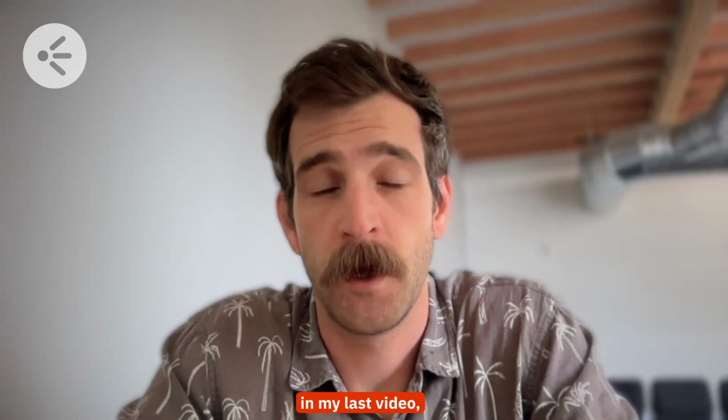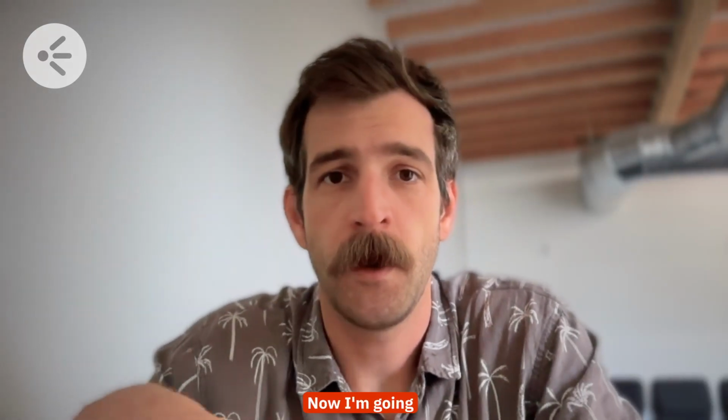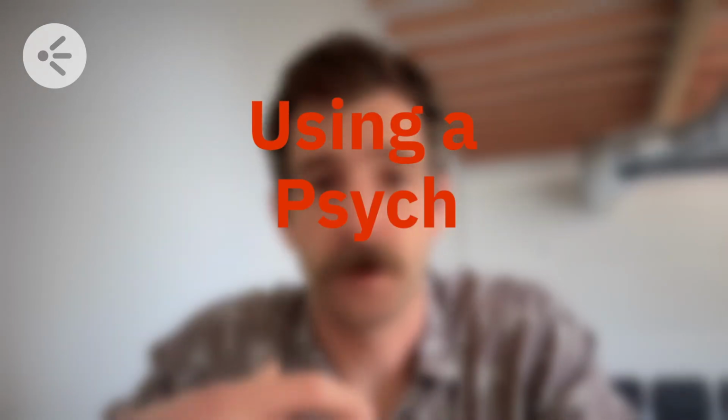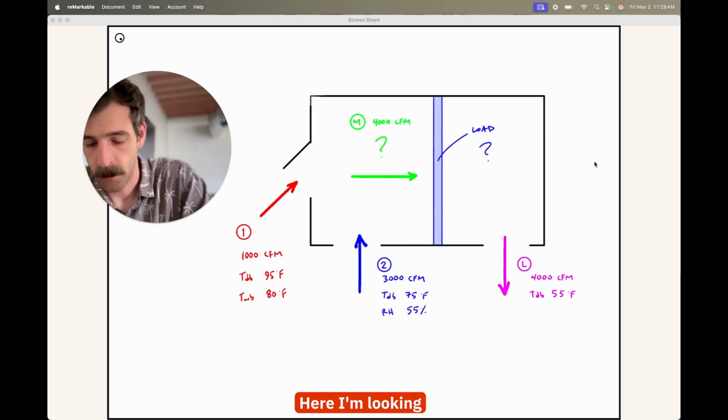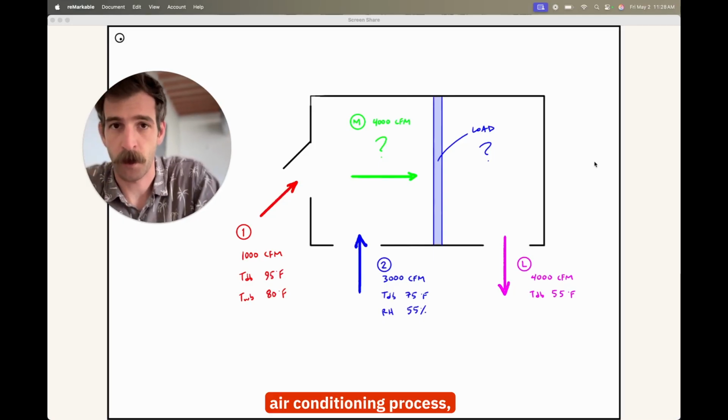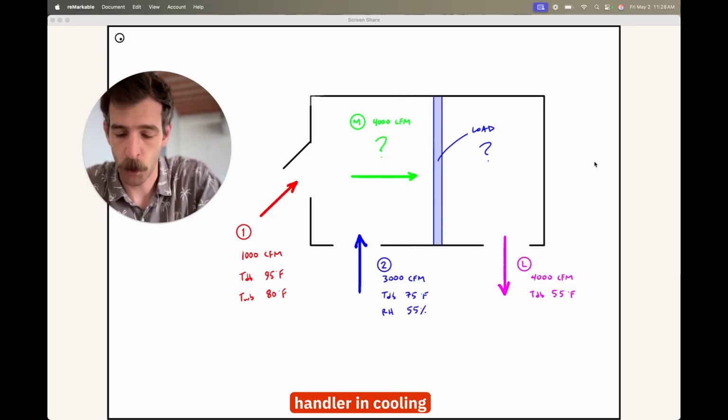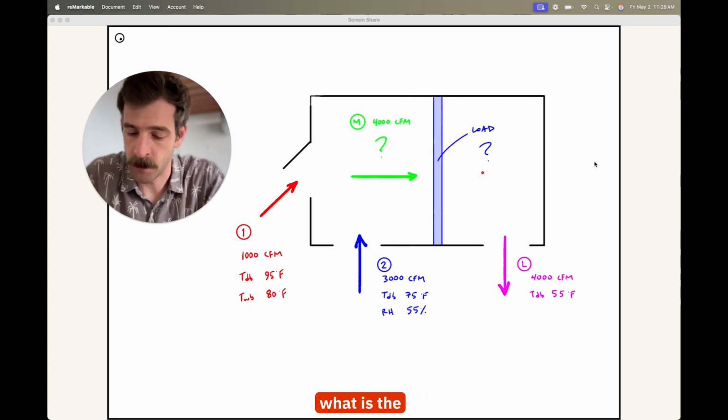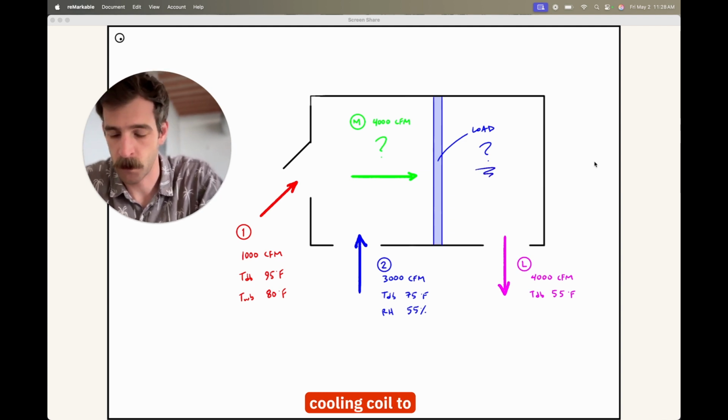Hey, in my last video, I talked about how to read a psych chart. Now I'm going to go over how I actually use a psych chart in a real world application. Here, I'm looking at a basic air conditioning process, a central air handler in cooling mode, and there are some things that I know, and then I'm going to use the psych chart to attain the things that I don't know. And really what I want here is, what is the load on this cooling coil to accomplish this process?